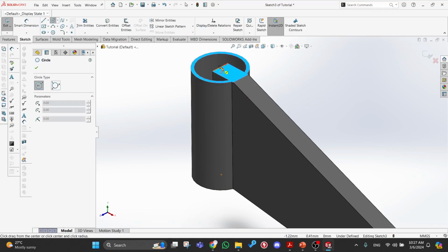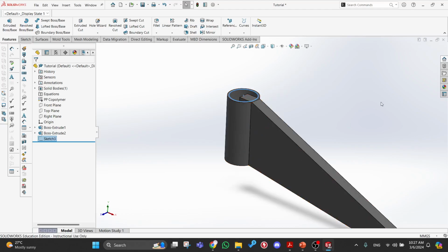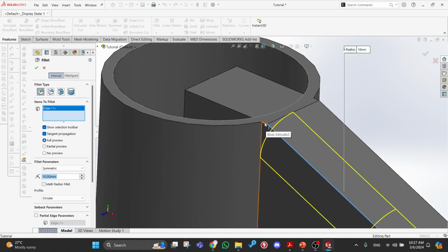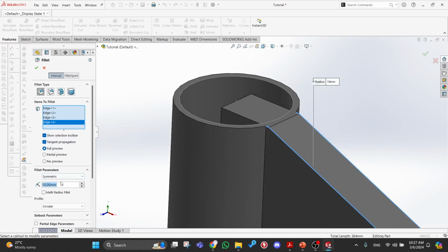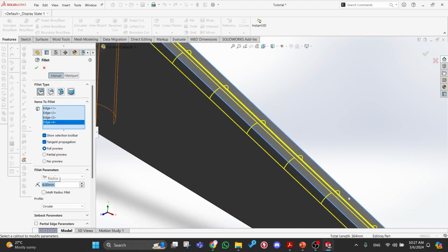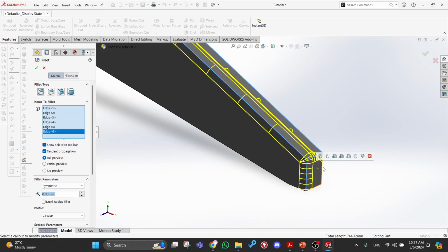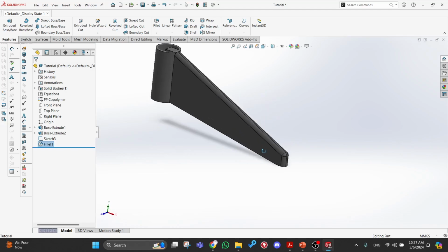We will cut this out. This is in preparation for later. So this is going to be here. Then we'll slice this later. Let's fillet this first, so that we don't have any too round of an edge. Twenty is a bit too much. Something like 8 instead. Yep, nice. Here. Okay. Done. Okay.